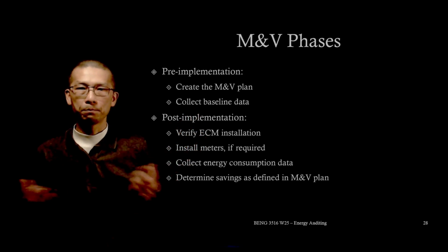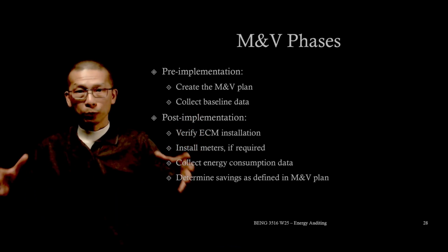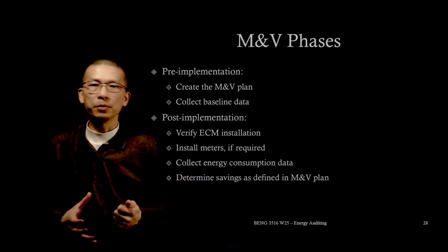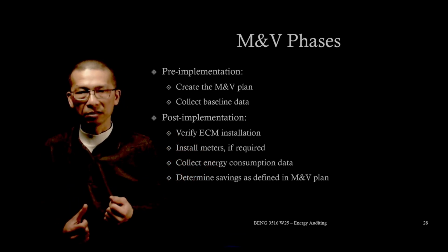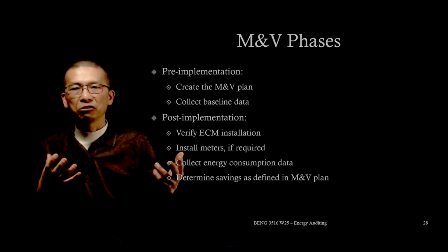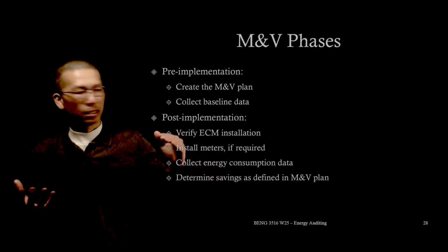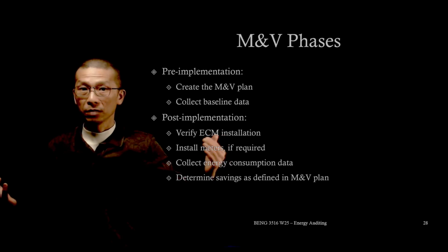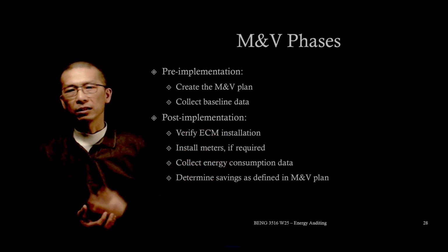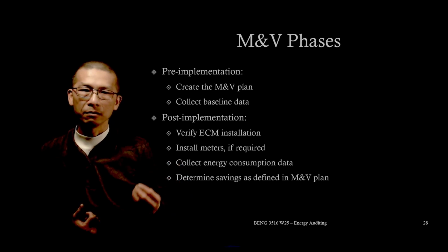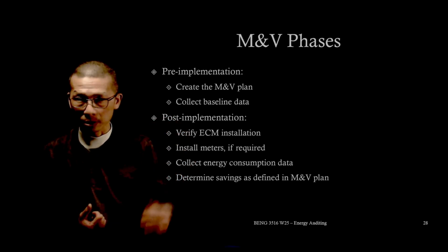Collect baseline data. We gather historical energy consumption data, utility bills, meter, sub-meter data under normal operation conditions. The baseline represents the business-as-usual scenario and serves as the reference point for calculating the savings, right? It sets the reference.